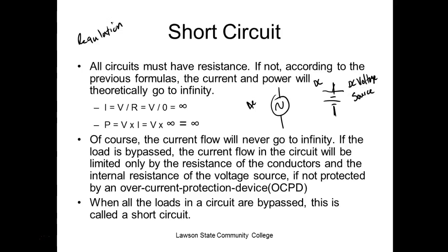What's happening is our regulator is putting in more energy. It's doing a technique that we don't talk about in this class. But what it does is the regulator looks at the output, and if the output tries to drop down, it puts more energy into the system and makes it go up. If it tries to go up, it takes away. So if we've got a regulated voltage source, the output maintained is fairly constant over the range of its operation.